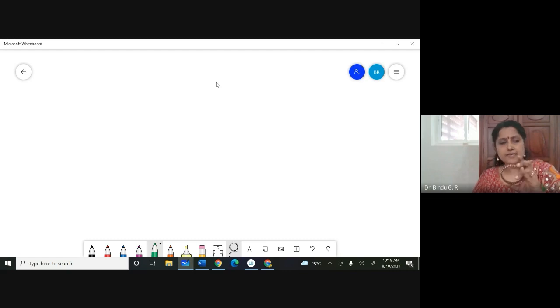In the other case, if it is an AC generator that you're speaking about, an AC generator has coils kept here. Coils are stationary. Within that coil, you have the magnetic field, magnets which are electromagnetic in nature, or permanent magnets. They will be rotated like this. When they are rotated, it is effectively changing the magnetic field. So that is statically induced.